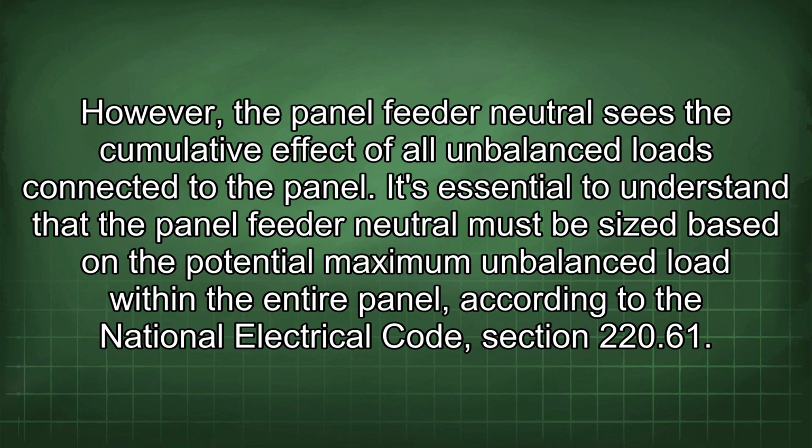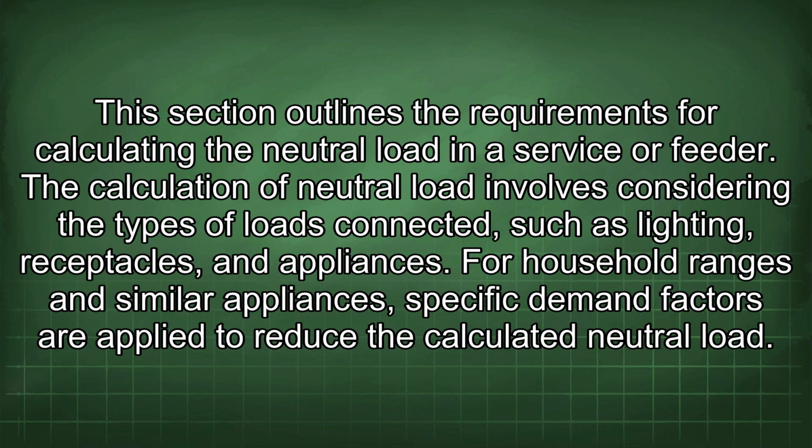It's essential to understand that the panel feeder neutral must be sized based on the potential maximum unbalanced load within the entire panel, according to the National Electrical Code, section 220.61. This section outlines the requirements for calculating the neutral load in a service or feeder.